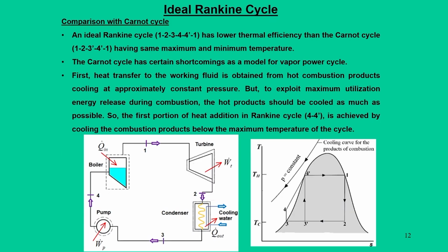First, I have already told that the work ratio, or work output, for the Rankine cycle is higher, but the thermal efficiency is lower in comparison with the Carnot cycle. This is already interpreted, but the other side of the story is that the Carnot cycle does not have much flexibility.